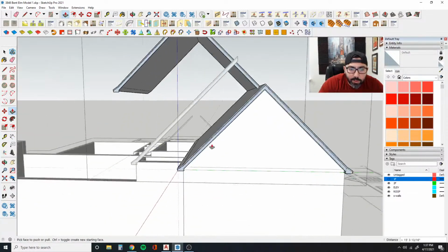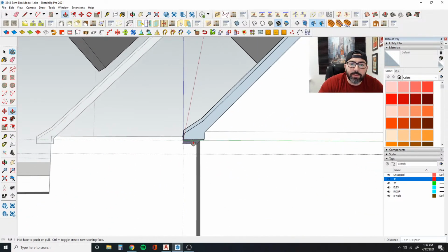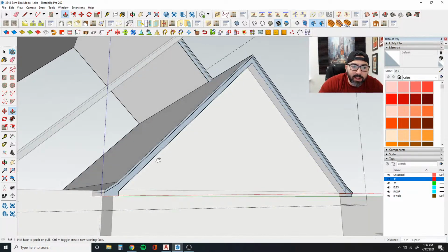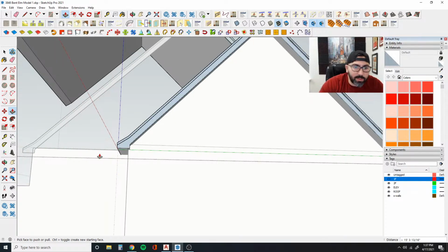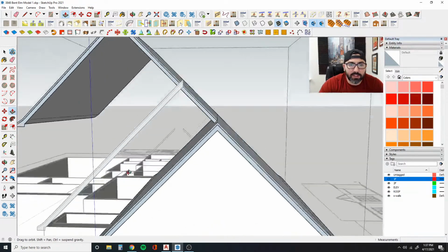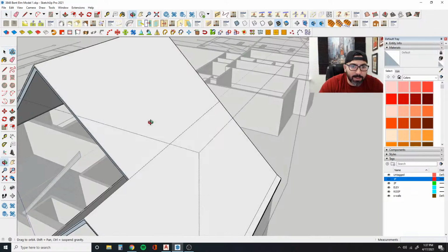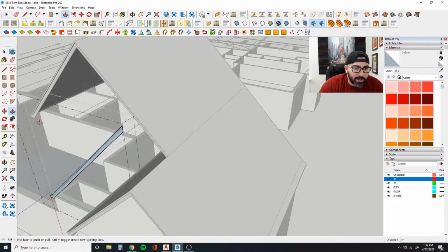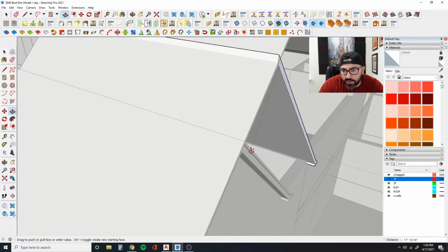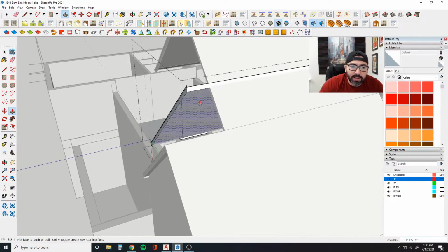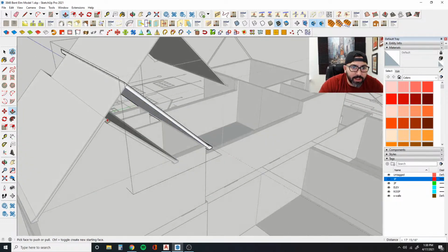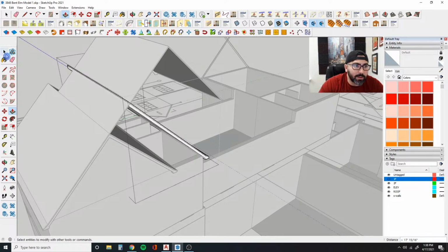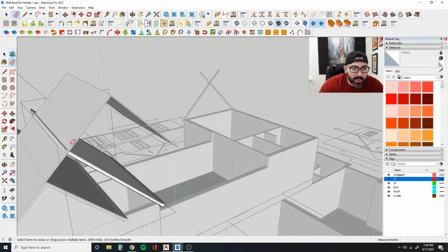That's the same thing with the eave overhang. So this is your eave overhang, and this is your gable end overhang. So the eave, the same thing. It could be 12 inches, which is fairly common, but it could be right on the wall as well. It could be 2 feet, 3 feet out. There's no rule that it has to be a certain size. You just have to have the proper ventilation for your attic, which could be in your soffits, or they have roof ridges that are vented. They have gable ends that could be vented. So there's different ways of getting around that.